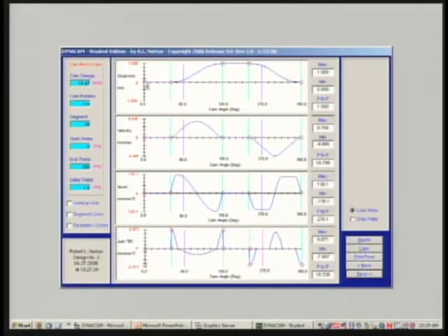You can see the dwell at 0, followed by a rise to the 1 inch, in this case, dwelling at 1 for 60 degrees, falling back the 1 inch over the last 120. The circles drawn here can be turned on and off with a switch down here. I suggest you probably want to leave them on because they're going to show you whether you have a problem. Look down here at the jerk.